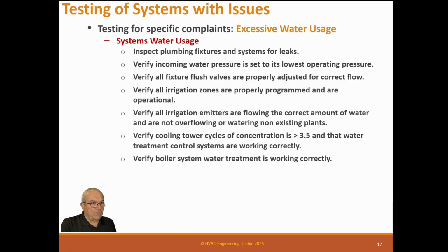Verify boiler system water treatment is working correctly. Boilers will foam, and when they foam, we have a whole bunch of drawdown on boilers. So we want to make sure that defoaming agent is working correctly. Verify if hose spray is used for cleaning. If they're complaining about their water usage and they're using spray hoses to wash off sidewalks and patios, tell them to try using air or brooms.